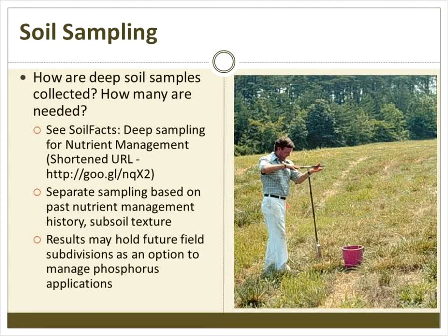And so here's the primer quickly on how to collect these deep soil samples. First of all, it would be advantageous for you to get the fact sheet on this. What you're going to have to do is core down to about 28 inches. Make sure you clean all of the soil out because you don't want any soil from the surface contaminating your deep soil sample.